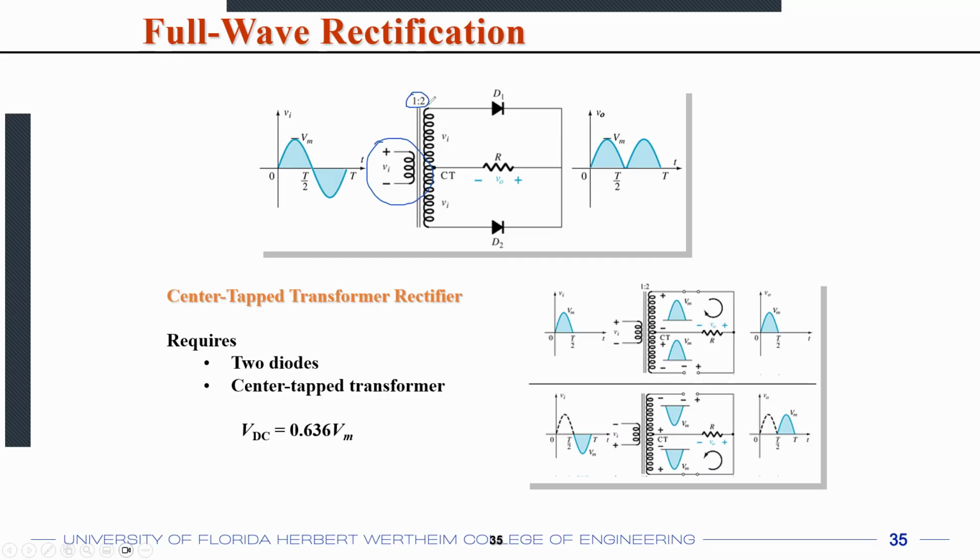Let's say that magnetic core makes sure that from the primary to secondary, you have a 1:2 voltage transformation, which means if the input voltage here is VI, at the secondary side, you'll create twice VI amount of voltage. Of course, you cannot create more power because this is a passive circuit. So if your voltage becomes double, your current becomes half, even in the ideal scenario, if there is no magnetic core loss in the transformer. So current will become half, but the voltage will become double.